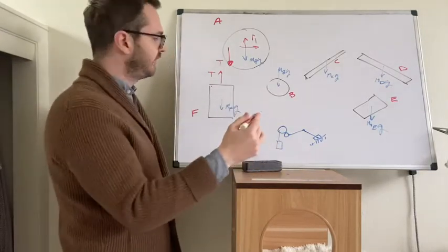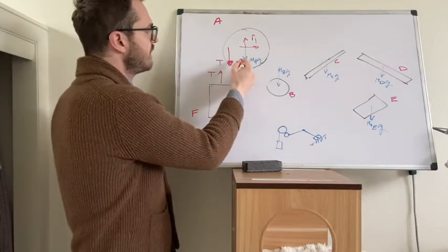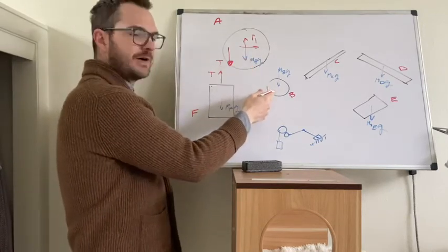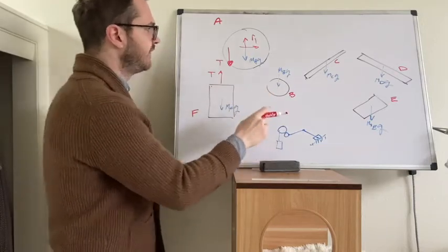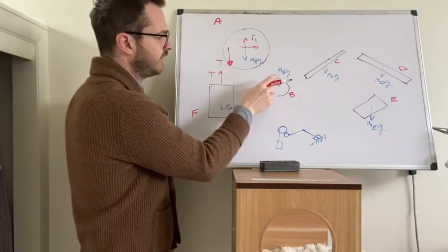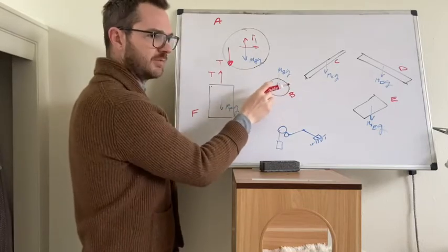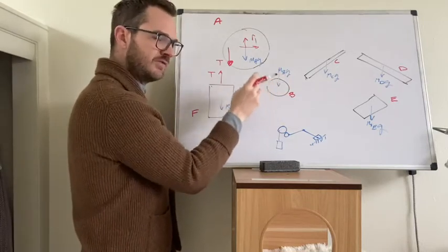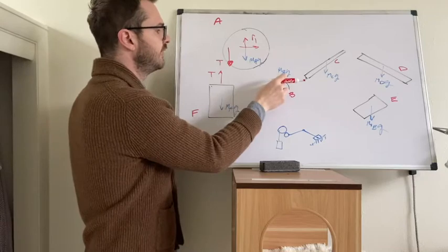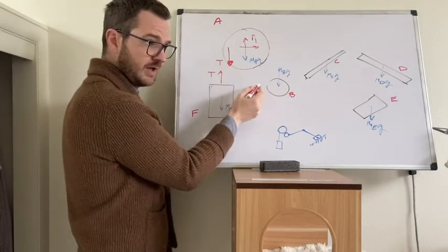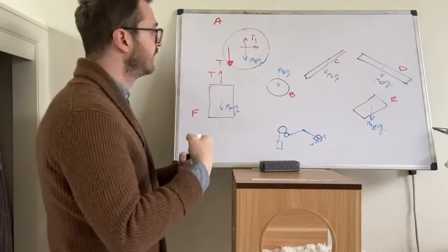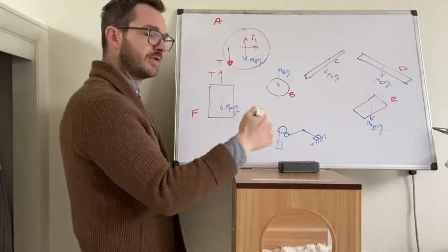What are the other joints? Well, the big disc is interference fit with the little disc, right? We talked a bit about what interference fit means. It means these two bodies, the coating around the outside, some kind of hard rubber, has been compressed just slightly, and then these two discs were mounted, and there's contact between the two discs, and they're being pushed against each other, which leads to a friction force.